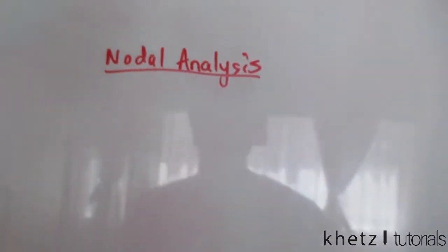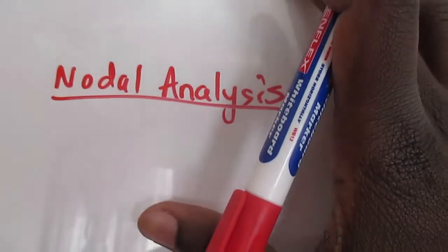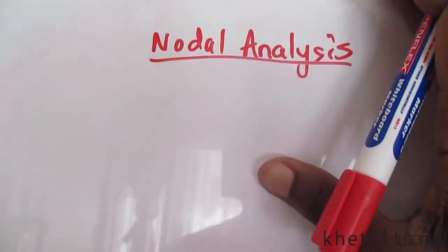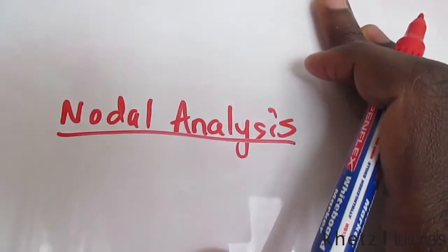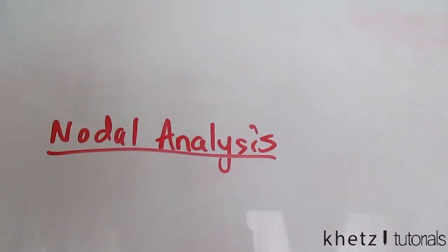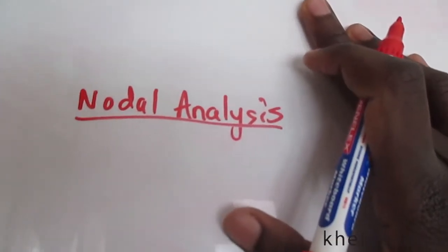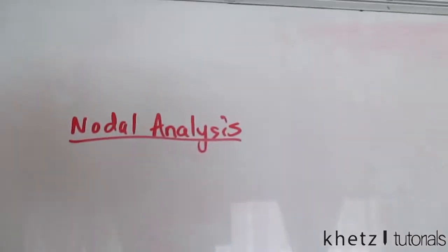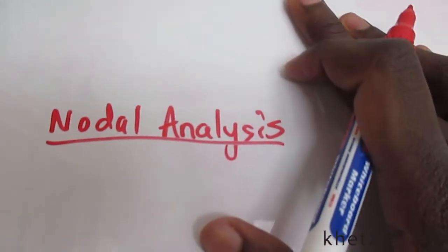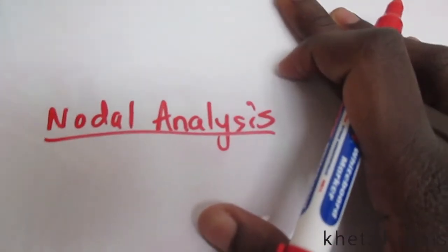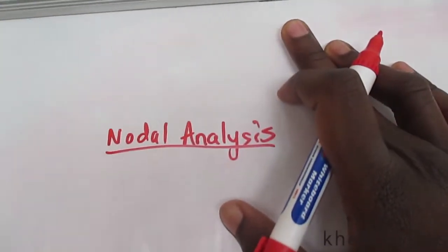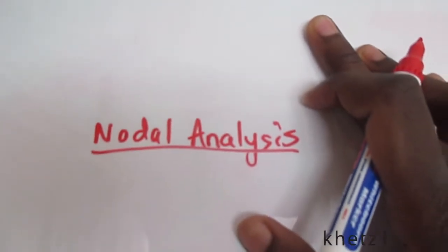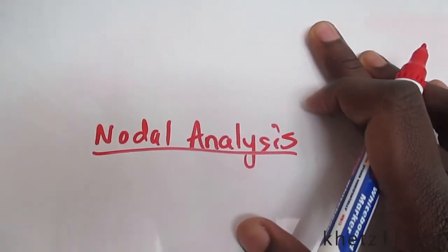Now, you might have used some methods to solve circuits or to analyze and find variables in your circuit before, and nodal analysis is basically the same thing, but it helps you to find those same variables by using node voltages as your variables. So you start by finding the node voltages and then move on to find whatever value you might be looking for. So I can split this into two cases, or at least two cases.